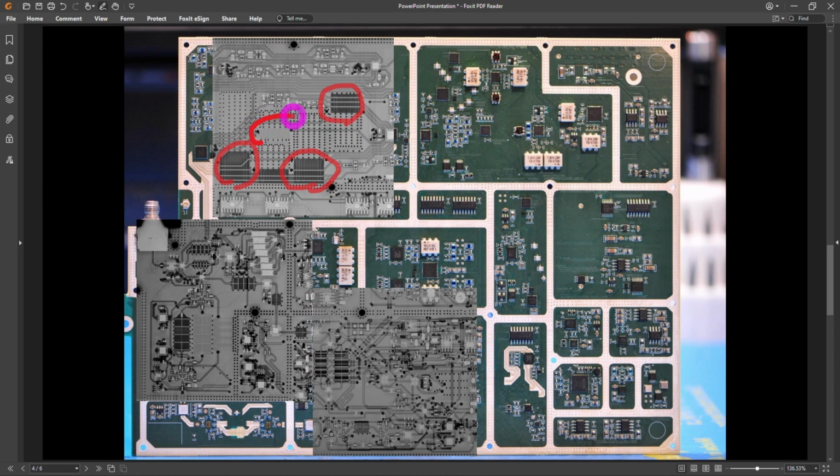There are even the ones that are in the intermediate layers. There's a little bit harder to see. There's some more hidden ones over here, hidden filters over here, some other match length lines over here, and all of these filters have to be individually characterized. And my X-ray only goes up to 35 kilovolts, so it's hard to see through these PCB layers because there's so many layers and there's so much metal to make sure that these things are isolated.